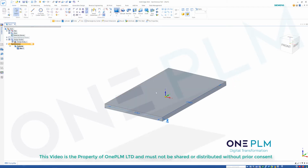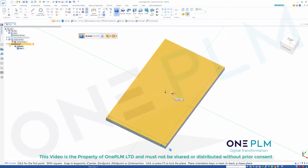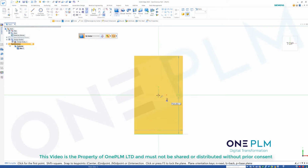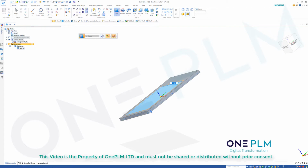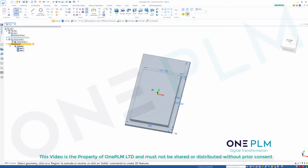Okay, next I'm going to do another box. So I'm going to do a Control T to get a top view. I'm doing my packaging, as I've got my little cutout at the top. So I'm going to drag that down there. Let's go about there, and then again drag up. I'm going to go 16mm this time. I'm now going to make some changes to my dimensions. So let's go 120mm, and we'll go 175.